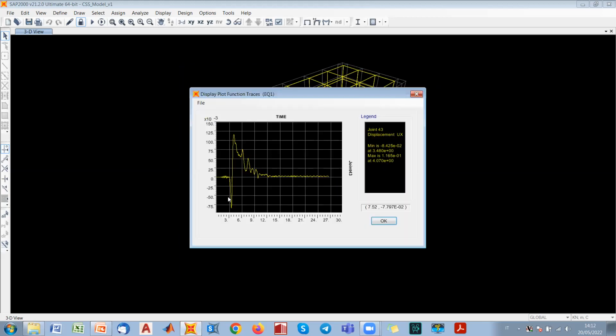This was the waveform, let's say, the results in terms of time series of displacement at the isolation level. And you see that here we have the maximum one, which is 116 millimeters. And yesterday I remember that we considered two strategies for the analytical modeling of curved surface sliders. If you remember, we implemented both the hyperbolic tangent and also the elastoplastic behavior for this typology of devices.